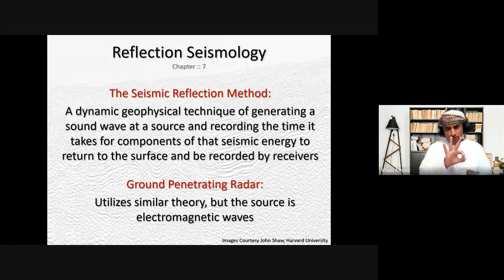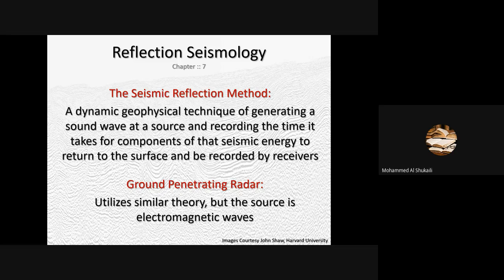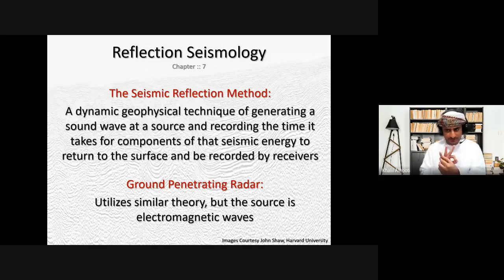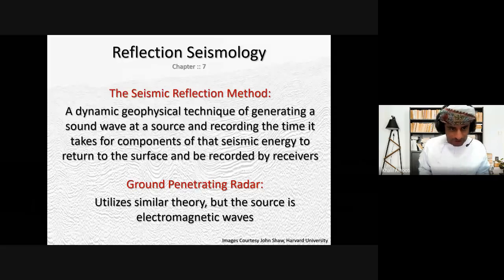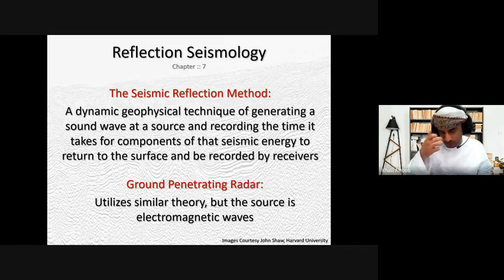So back to my question, which of these will penetrate deeper, the ground penetrating radar antenna of 100, 250, or 400? 100. Yes, that's true, 100, because, as Basma said, reflection goes deeper, and we know the frequency of seismic is low compared to ground penetrating radar.